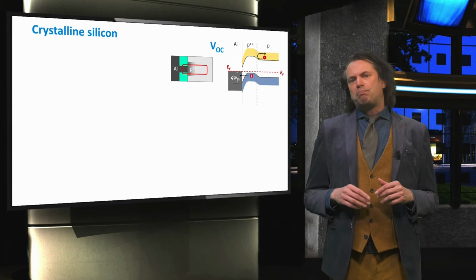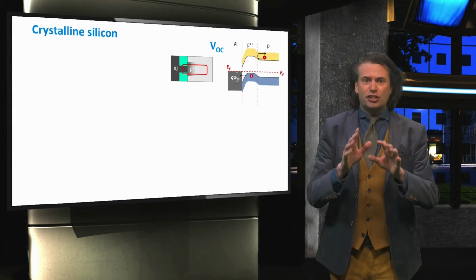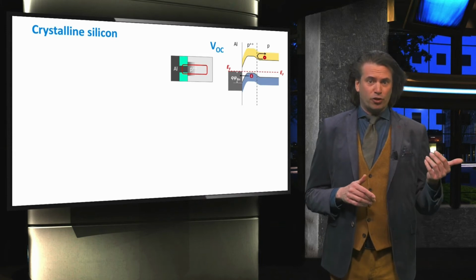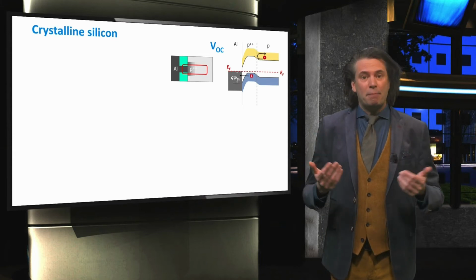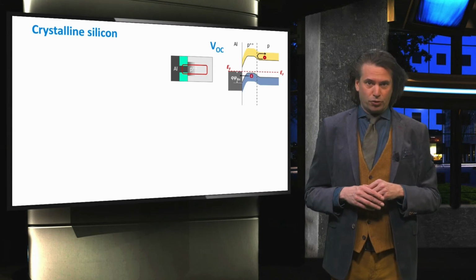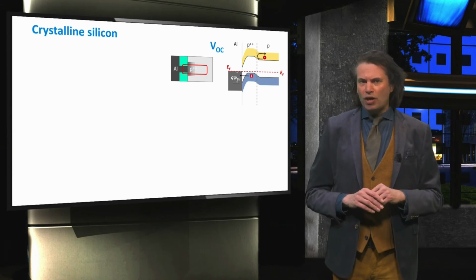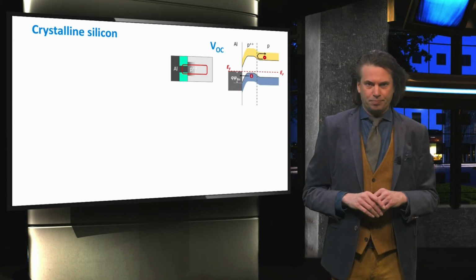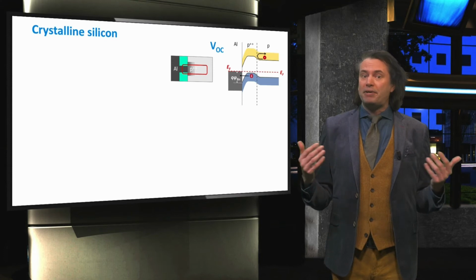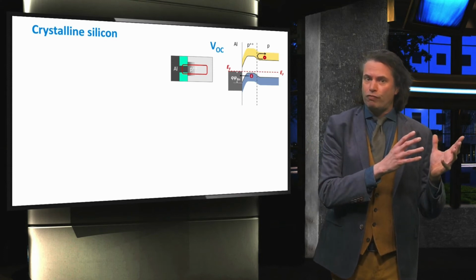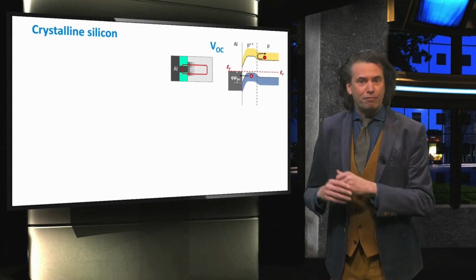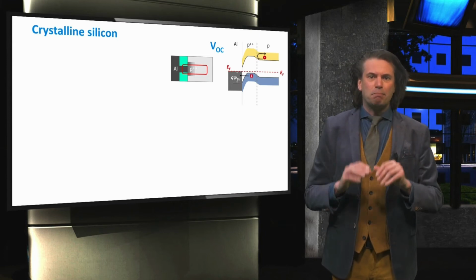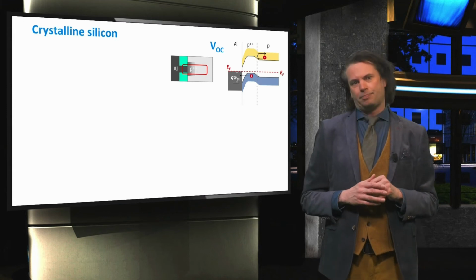In week 2 of PV2X, we have discussed the design considerations for crystalline silicon solar cells. The open circuit voltage benefits from a higher emitter or back surface field dopant concentration, which will lower the contact resistance between the metal contact and the silicon. We have discussed an empirical relation between the open circuit voltage and the maximum obtained fill factor, but that in reality, the fill factor is most affected by parasitic resistance.